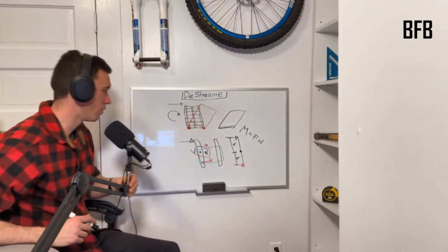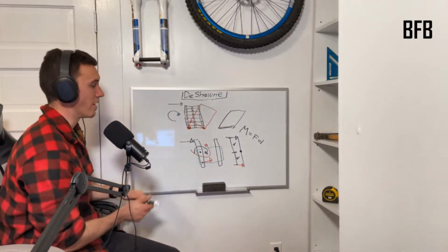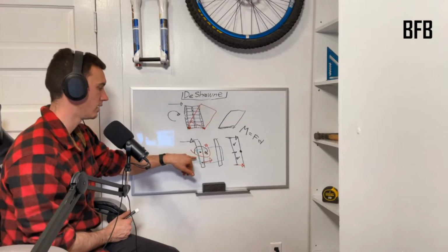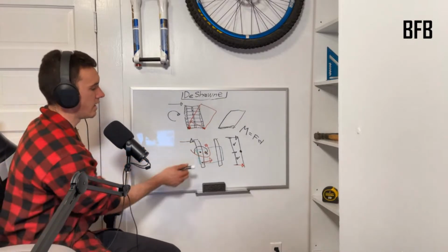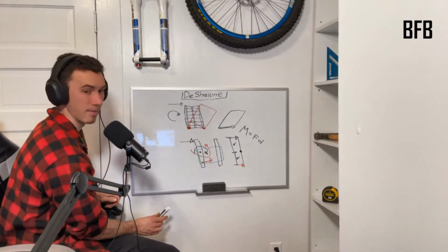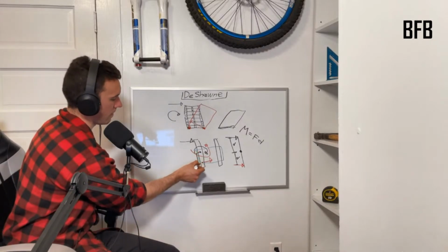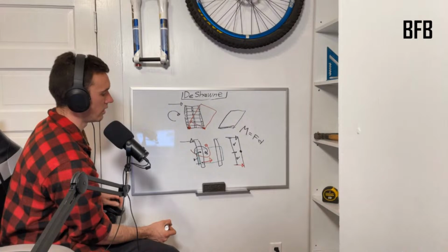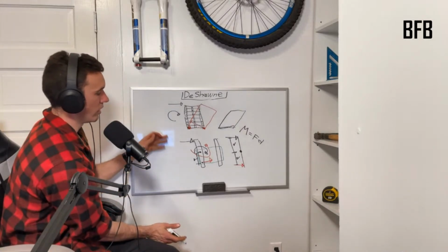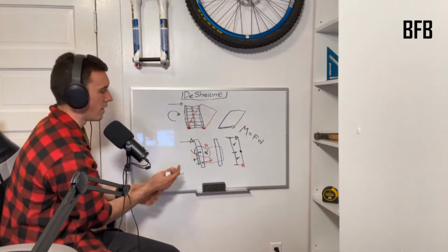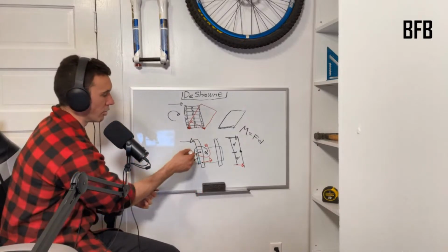So, when we go back to our deck plank, what we can do is associate strength from the plank to the stud. Because we installed this one plank and it's got this fastener and this fastener, and they are some distance apart, and we know the size of the wall, we know the size of everything, we know we've got 10 planks going up the wall, whatever, right? You can just multiply the numbers out and multiply by the number of studs.